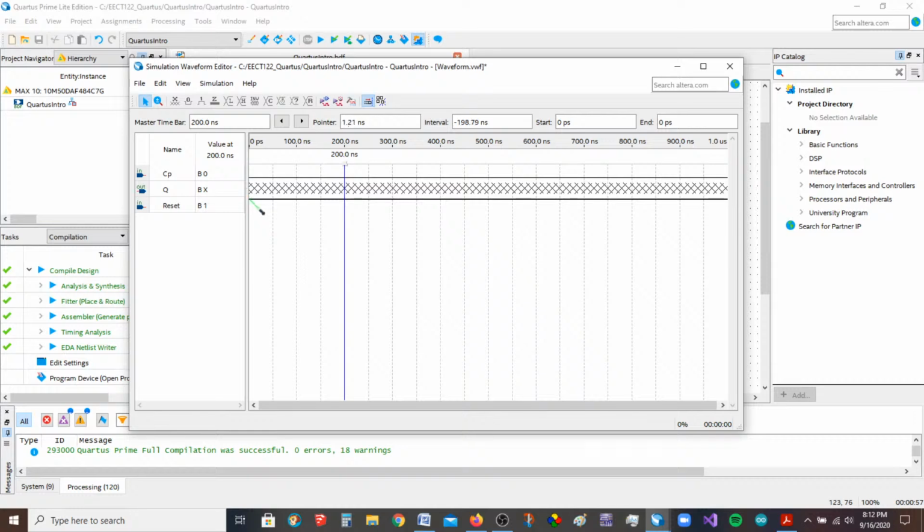So I'm going to make this one little section here, and this is the other reason I changed the grid size, because this goes by grid size. I can only do a 50 nanosecond section. If you want a smaller section, then you have to change your grid size. So I'm going to take that one little section that I have selected here and force that low so that I have an initial asynchronous reset, and then it doesn't affect the circuit the rest of the time. But it gives Q an initial value here. Otherwise, it's going to leave all hash marks on the output.